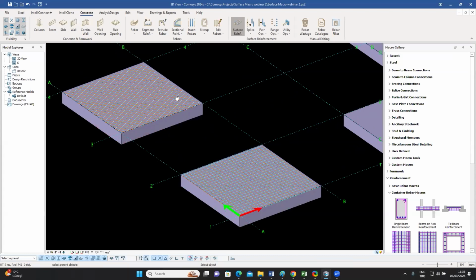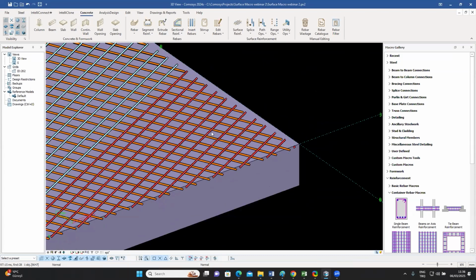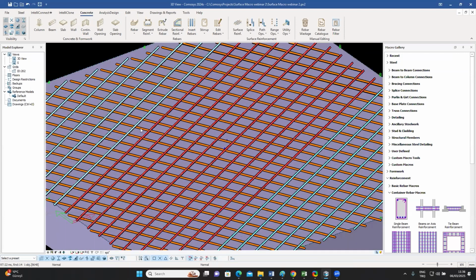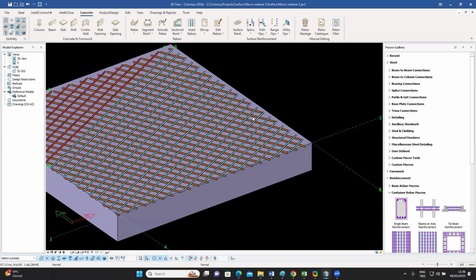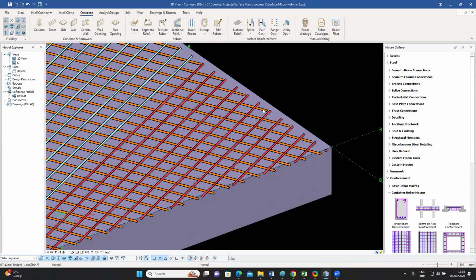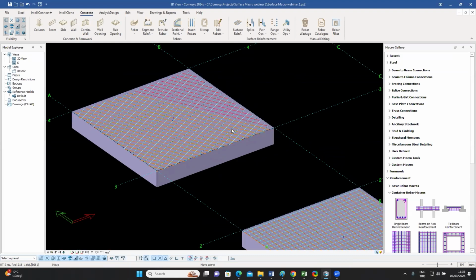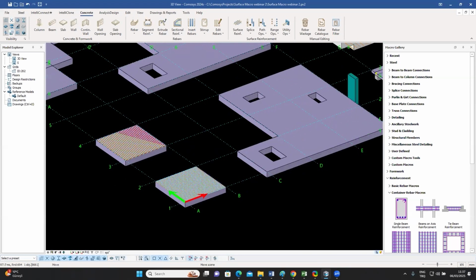If I show that, then my rebars are created in that direction, because the different part positions require these to be in separate parts. So by changing my direction for the main direction, I can create on the same surface, along a different direction, both the main and the secondary. Now, let's move on to more complicated cases.